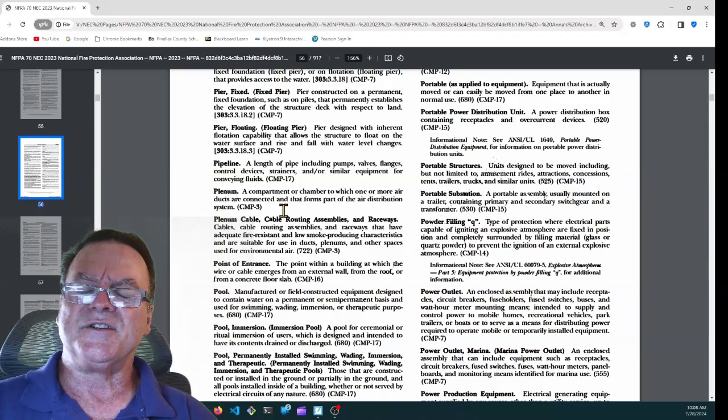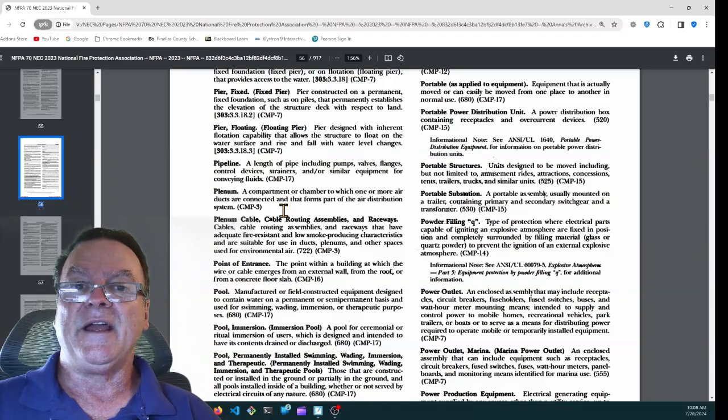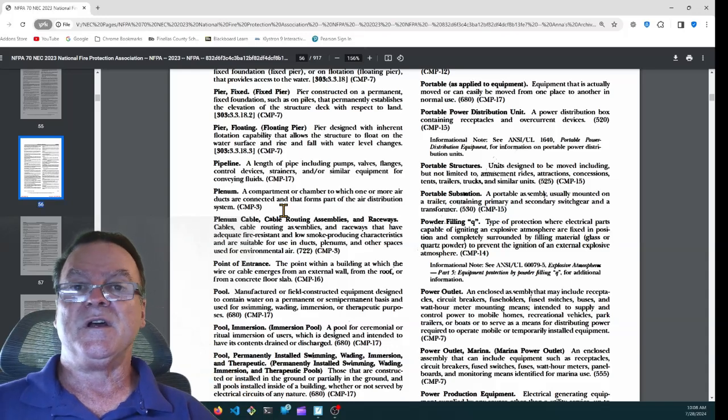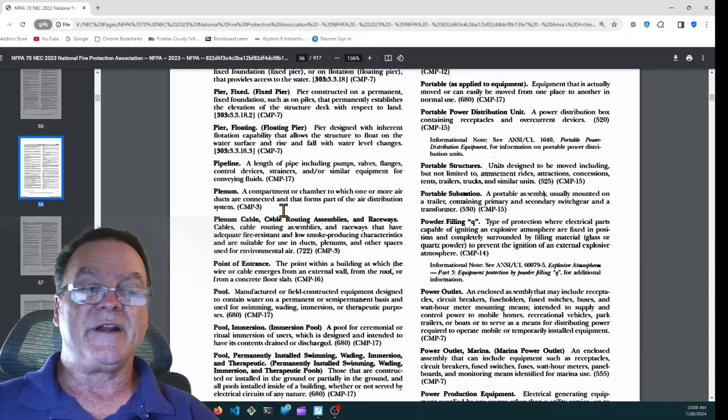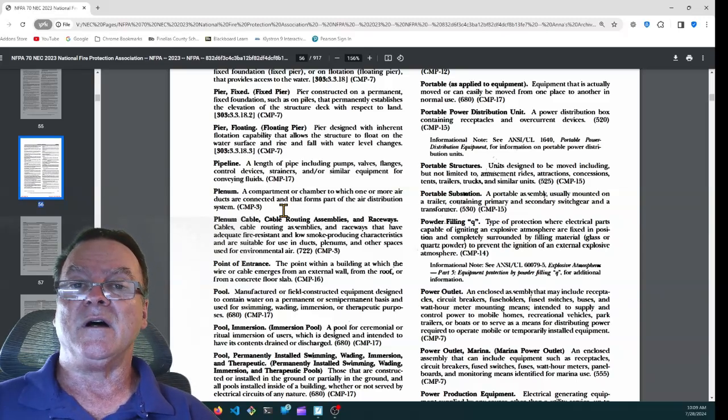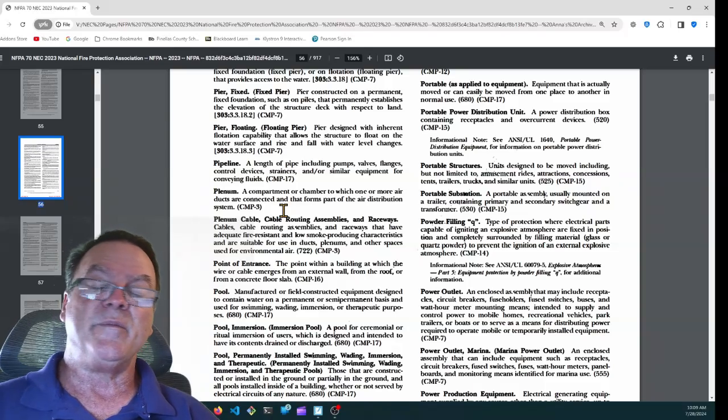I take it back, excuse me, we would not use liquid tight because the liquid tight actually has a coating on it that also gives off toxic fumes. So it wouldn't be plenum rated as well. We'd use flexible metal raceway with no coating on it, and we could put our conductors inside of that. That would be approved.